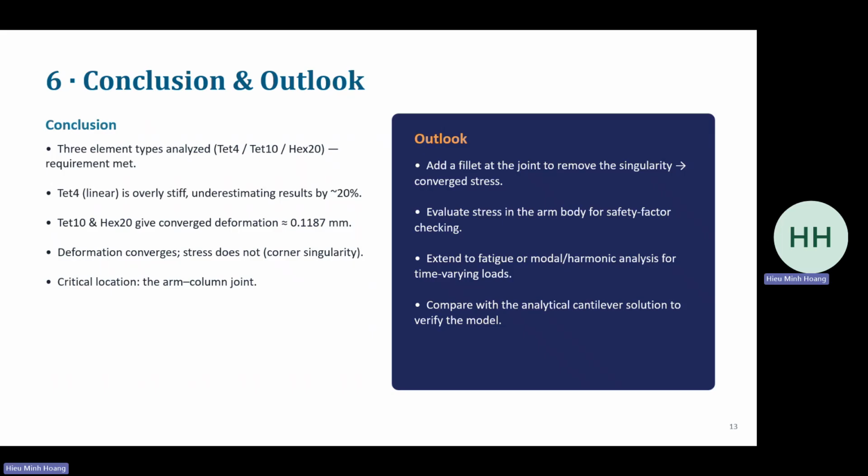For future work, I can add fillets at the joint to get a converged stress, evaluate the stress in the arm body for a safety factor, do a modal analysis, and compare with the analytical solution to verify the model.